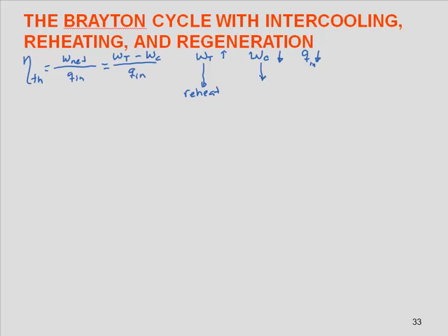For this will be the intercooling, and for this will be regeneration. We'll see that intercooling will reduce the amount of work, but at the same time will increase the amount of heat. So these two usually need to go hand in hand.